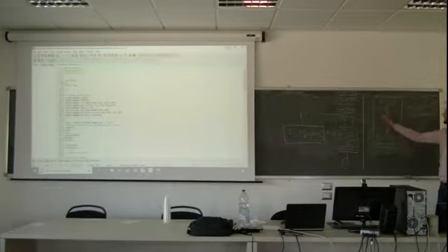Imagine this is one material and this is another. Maybe I want to add more nodes in one material than in another. Usually, you need more nodes depending on the gradients that you expect there. If you think that the gradients between two nodes will be low, you can reduce the number of nodes. If you expect high gradients, like for example in boundary layers, right?